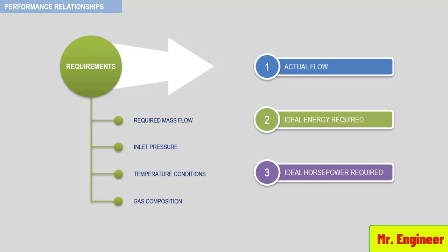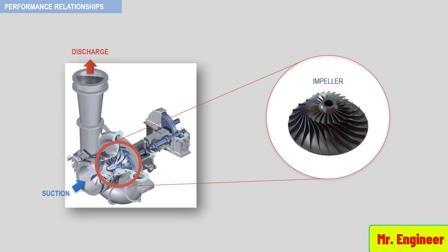Now, once the vendor obtains the data, the gas head can be calculated, and once the head and required flow are known, the impeller can be selected. The principle of impeller design is chiefly based on that of specific speed.